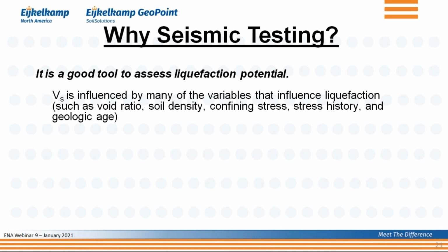And the reason for that is that it is a great tool to assess liquefaction potential. Let me explain to you. When you look at liquefaction, which means that the soil basically no longer has any bearing capacity, it's like quicksand, the parameters that influence liquefaction, and you see a whole bunch listed here on the screen, the void ratio, the soil density, and I can go on and on and on.